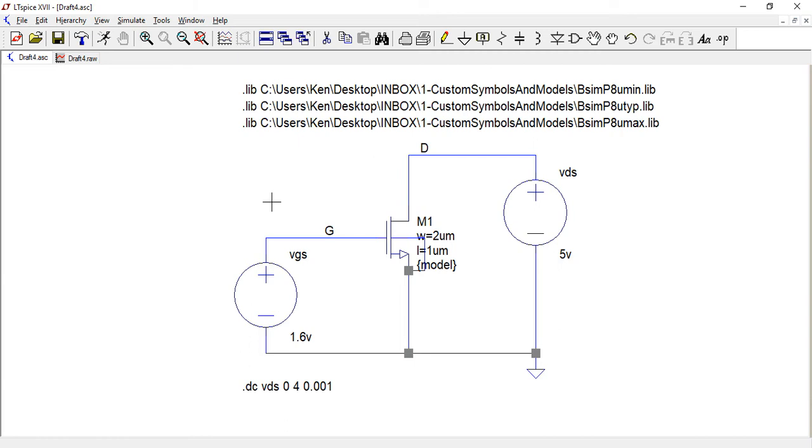And so now what we need to do is step this model through these three different values which you'll see contained in here. We already are familiar with the model called NMOS tip, and you'll find a model for the NMOS transistor in this file called NMOS tip. If you look in this file, you'll see the model name has been changed to NMOS min, and if you look in this file, you'll see the model name has been changed to NMOS max, representing the min, the tip, and the max of the process. But the problem is, the command that we'd normally use for this type of function is called .step. That's a standard SPICE command. .step does not allow you to step text, or I should say alpha characters. It only allows you to step numeric characters.